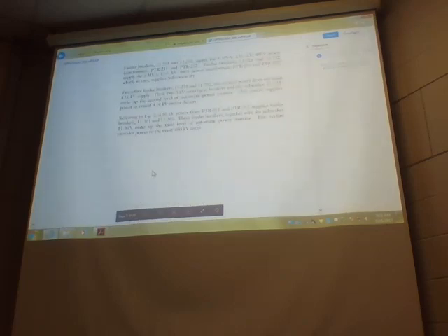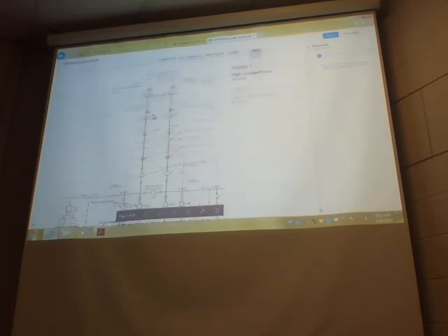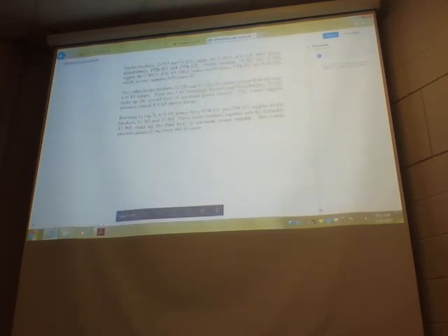The two other feeder breakers, 11231, 11232, also receive power from the main 4160 volt supply. These two 5 kilovolt switchgear breakers and the tie breaker, 11233, make up the second level of automatic power transfer. This system supplies power to critical 4160 volt motor drivers. So they were 11231 to 11232.